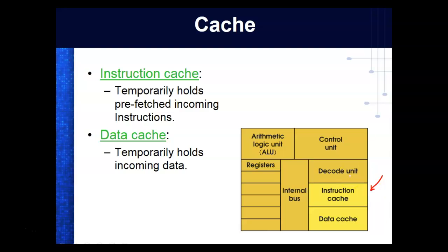so what the processor would do, in the old processors when you first started, it would switch into what we call the fetch phase. And it would go out, and whatever it pulled in was going to be an instruction. And this would be a binary number. Then it would switch to what we call the execute phase. And it would do whatever the instruction told it to do. And then it would switch back into the what? Fetch, execute, fetch, execute, fetch, execute, fetch, execute.